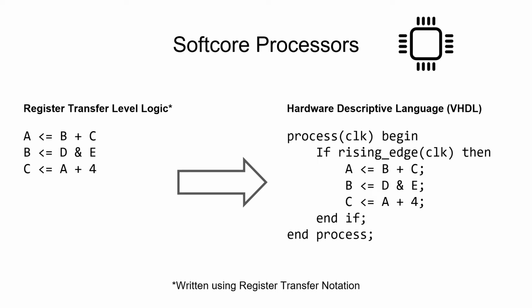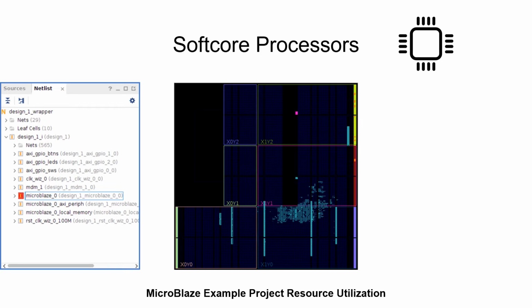The two main methods of implementing a processing system on an FPGA are by using a soft core processor or a hard core processor. A soft core processor is a solely software-defined processor. Now this is not software as is commonly understood. This is RTL, or register transfer logic, defined using an HDL, or hardware description language, that defines how the processor functions. A soft-core processor is not inherently separate on the FPGA's silicon from other custom logic. With that being said, it behaves as a separate entity within the FPGA, with regards to the other modules defined on the FPGA.